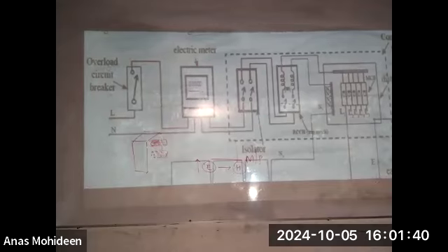So this comes in MCBs. There are two protective measures: one is MCB, the other one is RCCB. Only RCCB provides protection against electric shocks for residents, for the individuals, for the man. MCB does not. MCB provides protection towards the electric devices. Did you understand? Right, so two protective measures are there, one is RCCB, the other one is MCB.